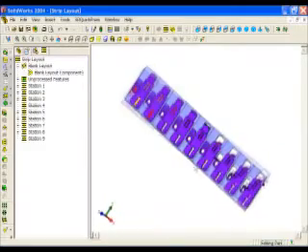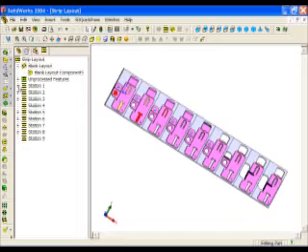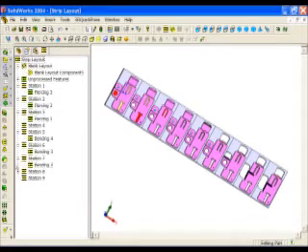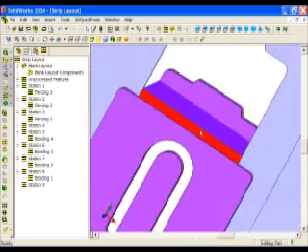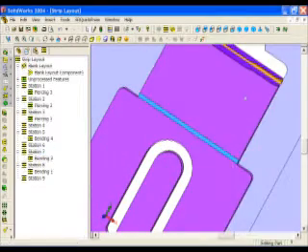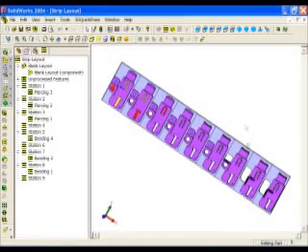You can see that very quickly it was laid out according to some simple parameters. Small piercings first, outer bends first, and then we can rearrange these at will. For instance, if we don't like where this bend is occurring, station 6, bend 3, we can inactivate it. As we zoom back out you see that 7, 8, and 9 are all updated.